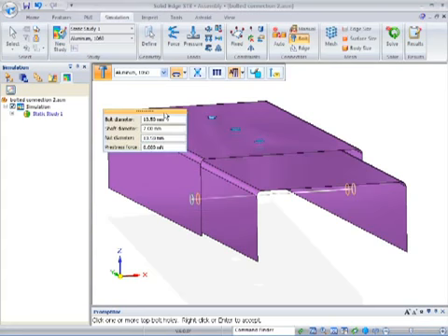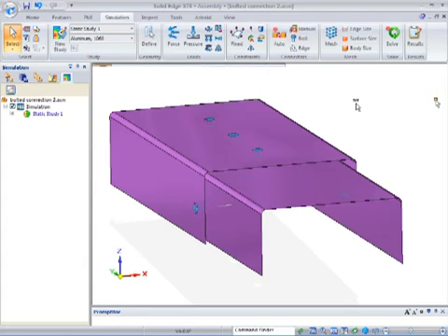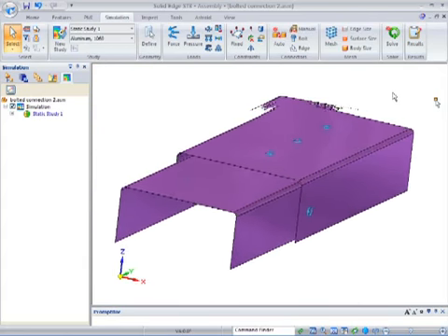And the exercise here really is to show you that if you need to change that search distance so it doesn't identify all of those holes at the same time, you simply click and hold and drag that search value back a little bit graphically. Key in your pre-stress value, right mouse button click to create the connector. Now I've got 5 connectors created for this part.